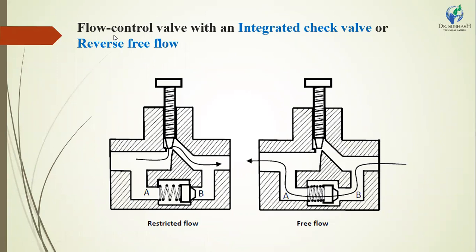The next is a flow control valve with an integral check valve, or reverse free flow. This valve is used to control the flow rate in one direction only. In the other direction, the flow is not controlled. It is a free flow.